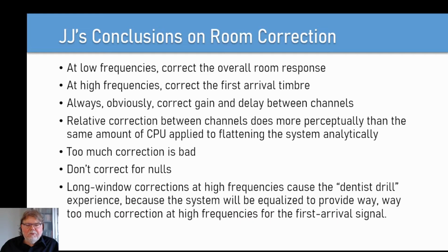Too much correction is bad. We don't want to correct for room nulls. And long window corrections at high frequencies cause the dentist drill experience because the system will be equalized to provide way too much correction at high frequencies for the first arrival signal.